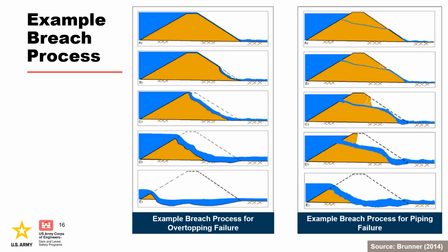During the piping flow process, erosion and head cutting will begin to occur on the downstream side as a result of flow exiting the pipe. As the piping hole grows larger, material above the hole will begin to slough off and fall into the moving water. Head cutting and material sloughing processes will continue to move back towards the upstream side while the piping hole continues to grow simultaneously.